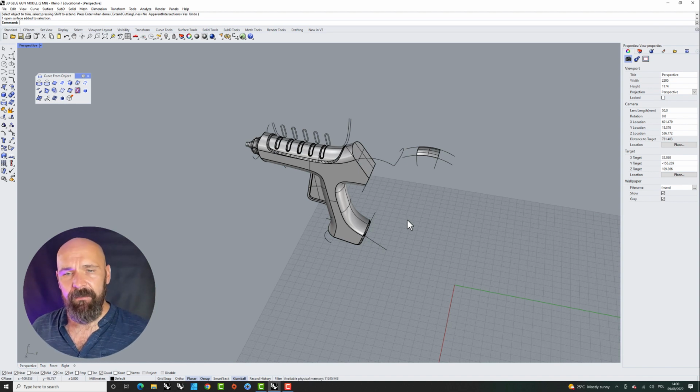That particular command is specifically useful for people who are printing, because as you probably know, the solid, when you're creating it, if you want to print it, must be kind of watertight. So every air, every water, whatever you close inside must be without holes where the water can go on. So you have to evaluate your solid after you design it. So I can actually evaluate that particular part.